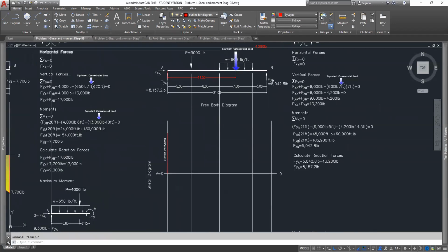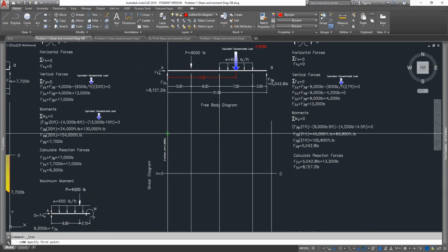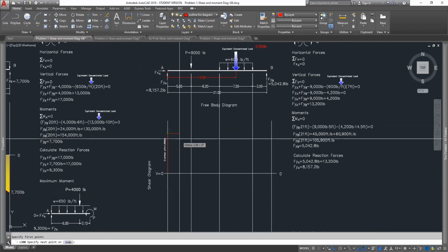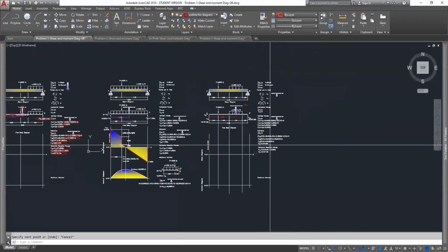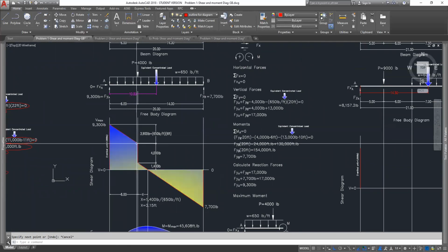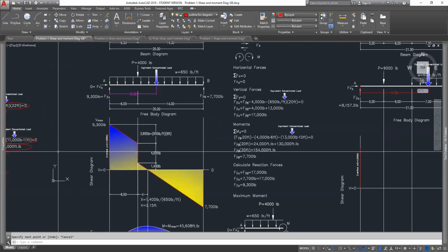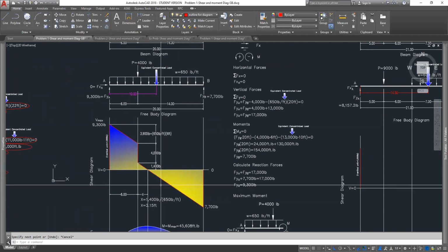All right, so from our point where we were, we went up 8157.2. Now, this is a little bit different than what you did in the example problem next to it. If we take a look at this, why do you think this was going down at an angle throughout the entire length from first support to back support over in here on this shear diagram?